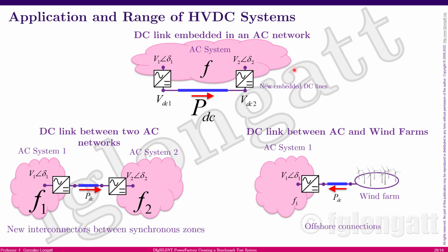As you must be aware, there are different types of HVDC links. There are different applications. For instance, if you need to interconnect two different areas with different frequencies, you can use a classical HVDC point-to-point connection, but there are also new applications like the integration of offshore wind power using undersea cables. The point-to-point interconnection has been quite useful, especially when we are using different frequencies. That is the case, for instance, of the example from Brazil, Itaipu, that is connecting Brazil and Paraguay, and it has been very well developed.